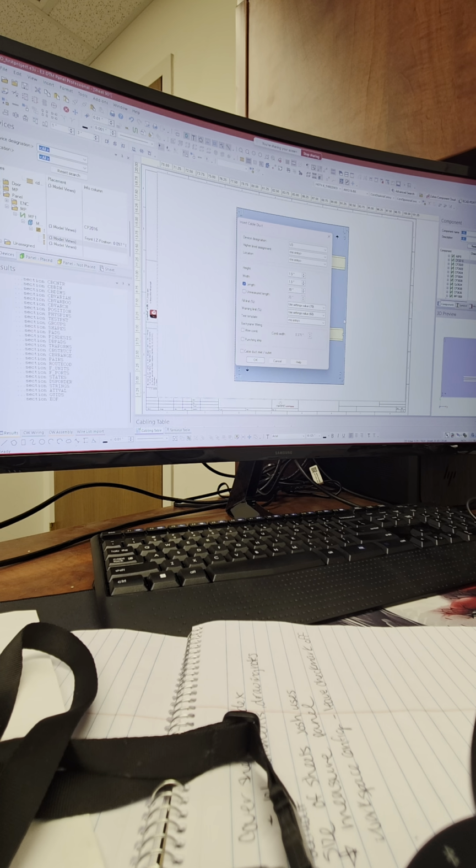So in this case, let's just make that length, I don't know, let's just say 8 inches or so to make sure it fits both on the plane. It's slightly longer than the thin rail itself. And the text template, this is the option where you can choose in that drop-down menu what kind of text marker, text type, and what kind of text do you want to show on your duct itself. So as a baseline, select the text C. It's kind of like the one that has the most basic info on it. Once you place it, I'll show what that is. Yes, this is all good. Click OK and place it.